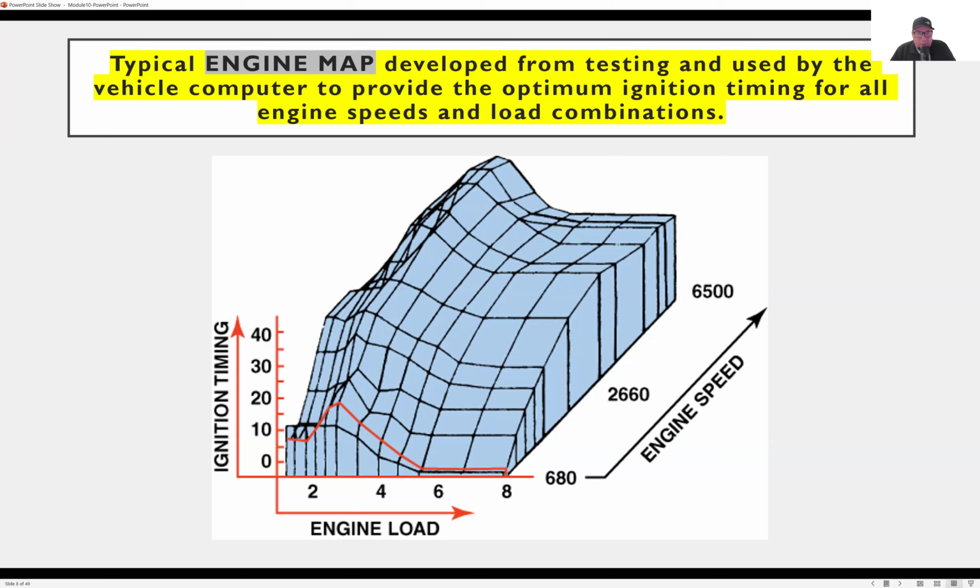different variations. Now, the engine map is determined by what the optimal conditions are for the engine to produce the least amount of emissions. It is not for the most power. There are maps for that, or programs, you can say. You can think of an engine map as an engine program. If you want the most power, there's a map for that. If you want the least amount of pollution or emissions coming out of the tailpipe, there's a map for that. And that's what the manufacturer creates for the vehicles, to pollute the least amount.